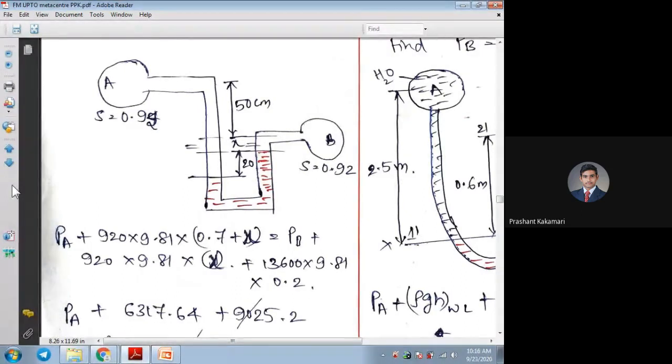And the liquid head for the B pipe, which with respect to A is rising, or is at the above point, you can consider on the right side with positive sign, or if you take it on the left side, take it as negative sign, because pressure A and pressure B are acting opposite. Are you understanding? So either you can write PA minus PB, then the heads of all the liquids with respect to pressure equations all on one side, positive and negative, and make it equal.